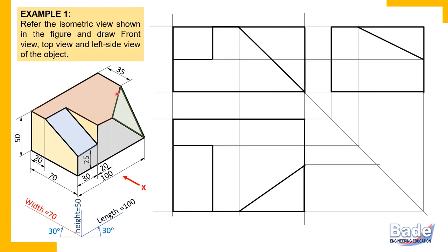Now we got this corner, and this corner, this corner, and this corner. These three corners are to be connected. Okay. Now let's focus on this corner. Where is this corner? So first thing is, this corner is at top and on the front. So at top and on the front, whether this corner is at extreme right or extreme left or in between, you need not worry about its position along the length axis, because length does not appear.